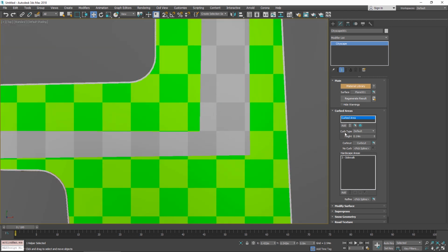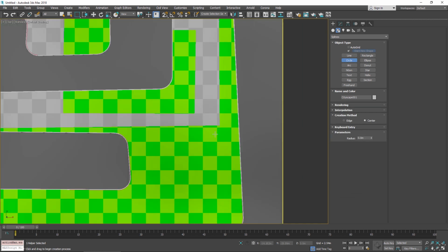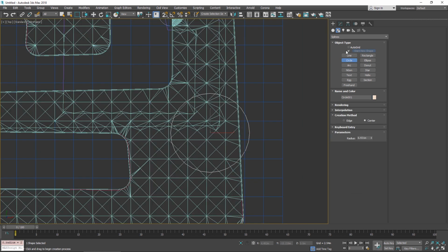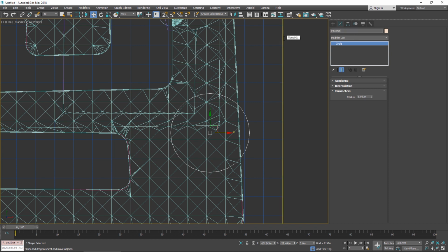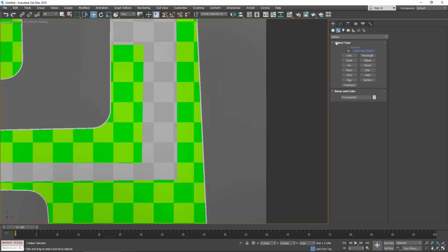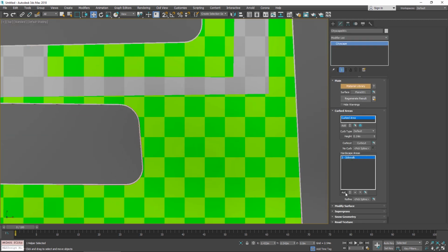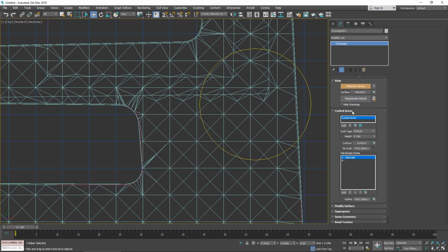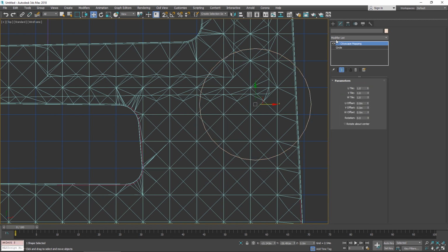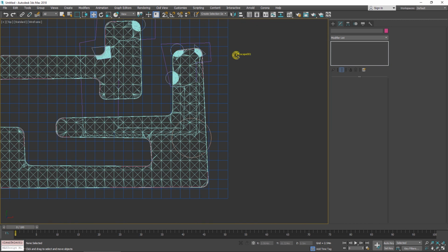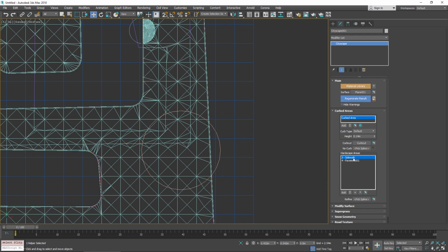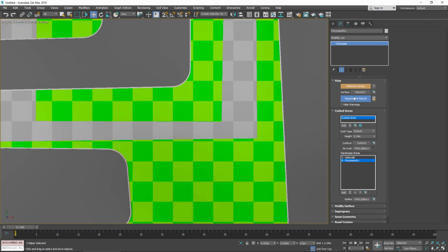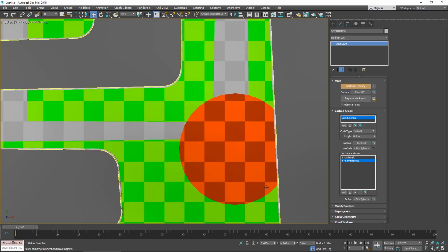So let's just keep adding more hardscape areas. This time let's just do a circle, and let's call it pavement 1. I probably didn't put the spline name in. Okay. So every time you update the spline name, it will automatically get updated in the interface. So let's just generate. And you can see that the new material ID has been generated for that area.